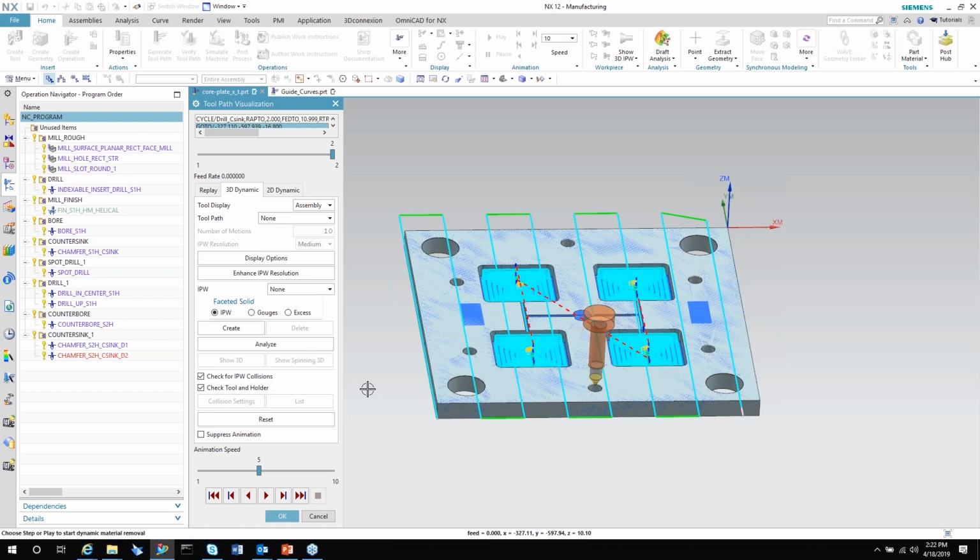And what we found is they're at least 25% faster doing it with common tooling, even if it's, say, these large 75 millimeter holes. That customer would have a 63 millimeter insert drill and then a 3/4 inch carbide roughing end mill, 3/4 inch carbide finishing end mill. And feature-based machining would pick those tools and generate the operations with those tools instead of the tools that it picks just from the out-of-the-box machining knowledge editor. And by doing that, it makes your plate programming fully automatic. They can do this feature-based programming start to finish, and it uses common operations, common tooling that's already in the machine. They know they don't have to set anything up other than the part.